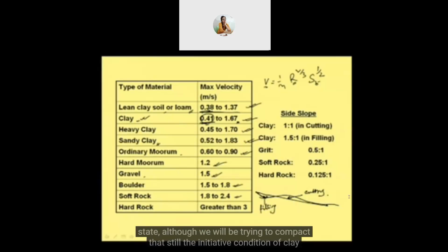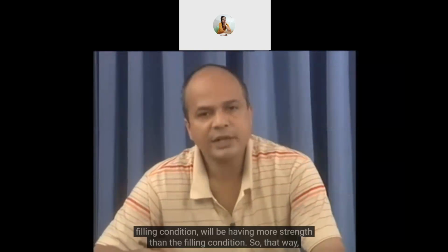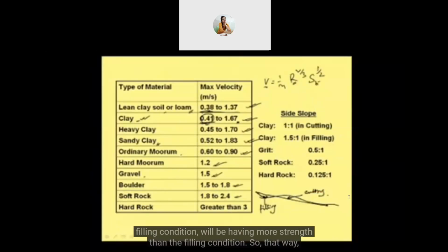Although we will be trying to compact that, still the in situ condition of clay will be having more strength than the filling condition.